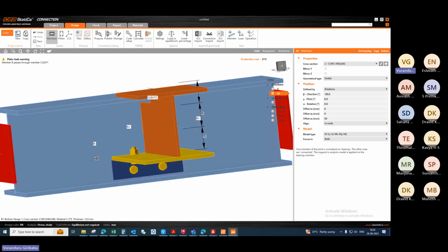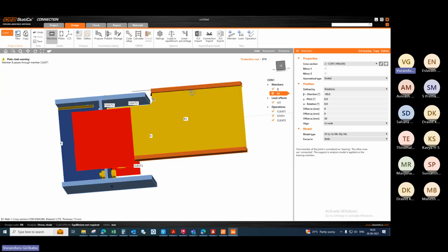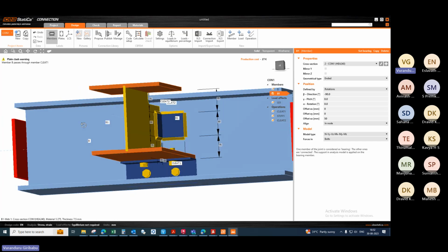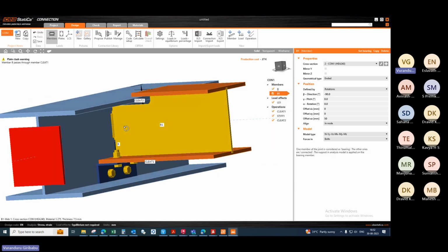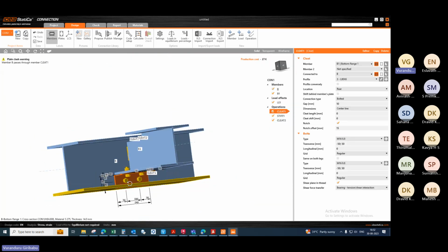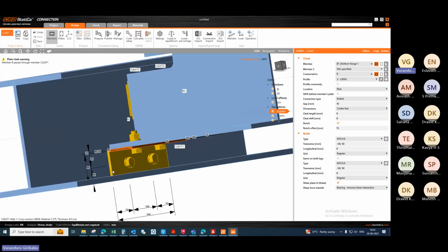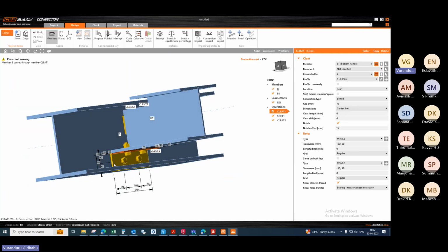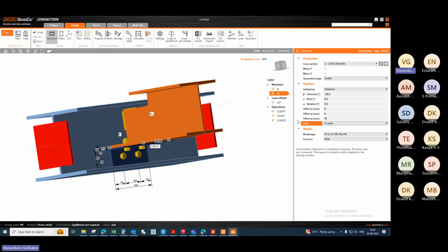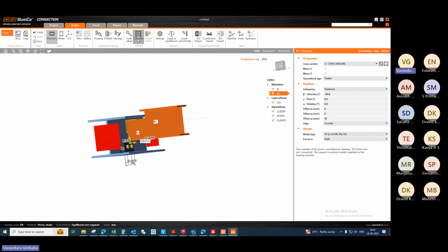Oh, the section is welded already to the web. That's fine. But if it is not welded in the top, we can leave it like that. We can run the analysis as of now. But the member passes through the member cleat. The member cleat itself is still not in; it is passing through the member. We still have to give the clearance. Otherwise, we have to reduce the cleat length. So we'll give 70 still. Okay.